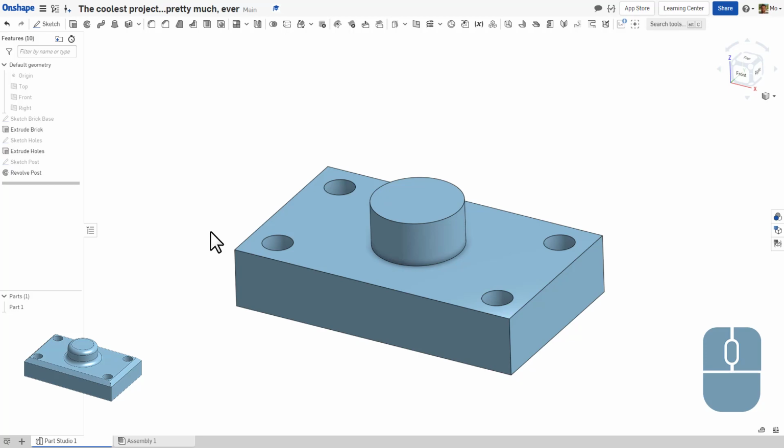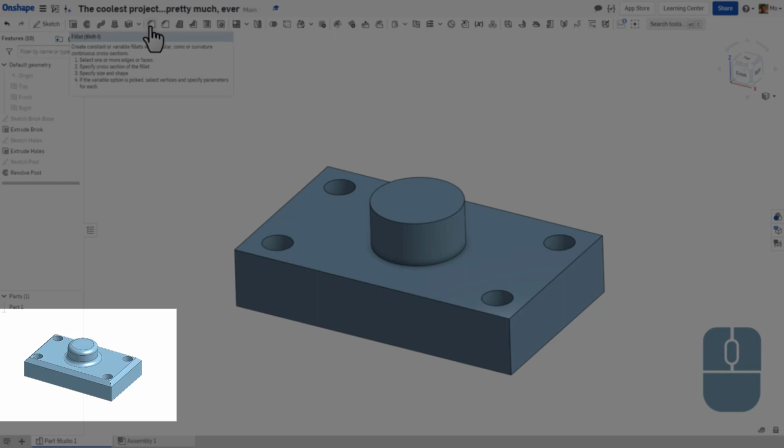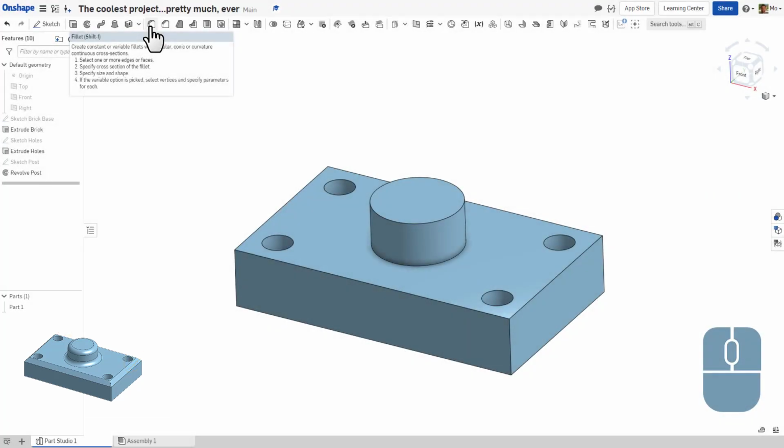So, what's left? You may notice that the picture of our goal shows that there are some curved and sanded down edges to our part. Why would we do this? Well, I'll talk while we start to model, but to show you exactly what I'm going to do, I'm going to use this Fillet Tool and the Chamfer tool. Chamfers are flat edges, where fillets are rounded edges.